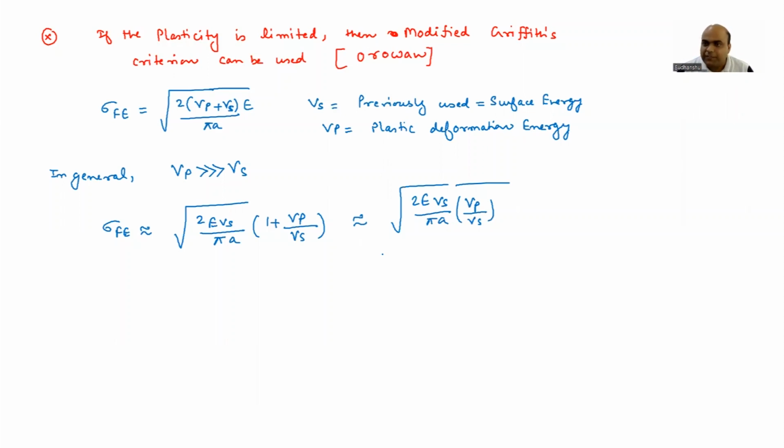Okay. So overall, what we have done till now, we have introduced the concept of both Inglis criteria as well as Griffith criteria. One is stress based, another one is energy based. Okay, and both are related to the calculation of the fracture stress, and both are showing actually that the fracture stress is much lower than the calculated theoretical stress, which is in GPa. Okay, and finally we have compared the Griffith criteria and the Inglis criteria, which one we can use while calculating the fracture stress. Okay, so let me stop here. We'll meet next time. Thank you.